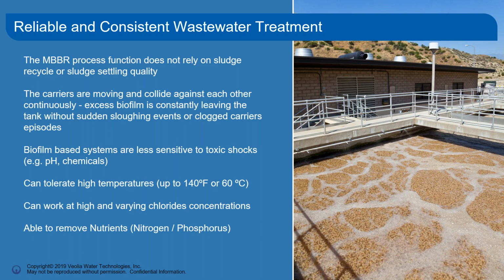And nutrient removal is possible. In the pulp and paper industry, we normally have fewer nutrients in the water than we need for the biological system. But still, when adding the nutrients you need, it's very important to have a control so you don't have too much going out, because we see the strict regulations now coming in many, many places. In Sweden, we need to be sometimes below 0.15 milligrams per liter phosphorus, for example, and maybe 4 milligrams per liter nitrogen. So even if they're not high concentrations from the beginning, we need to be careful with what we're dosing, and we can control that very well with this type of technology.